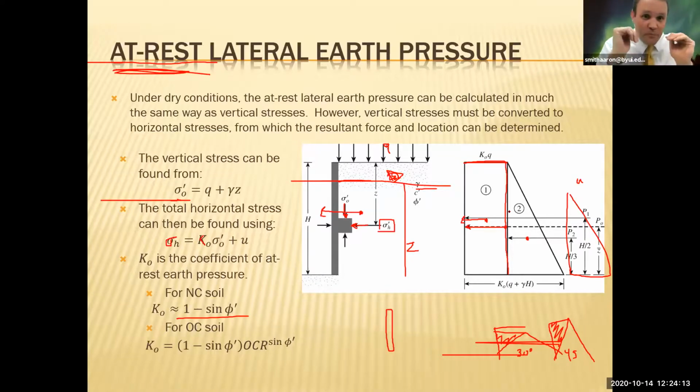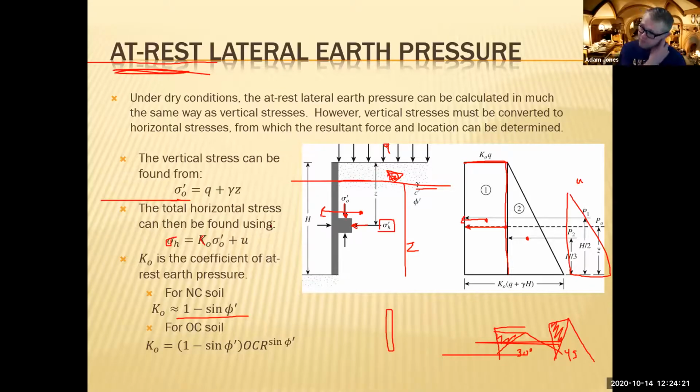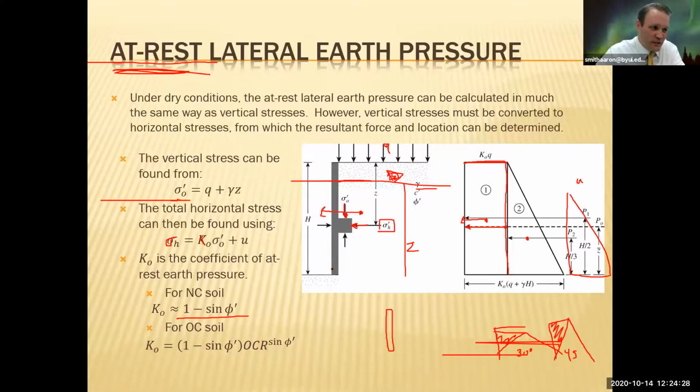That's why when people design walls, they try to put weep holes. Has anyone heard of a weep hole before? What's a weep hole? It lets the water flow through the wall, but it holds the soil back. Yes, it's as simple as drilling little holes in the face of your wall, so that if there is a water table, or if it rains or you're watering your lawn, instead of building up a water table behind the wall, the water can find a drain, like a bathtub drain.